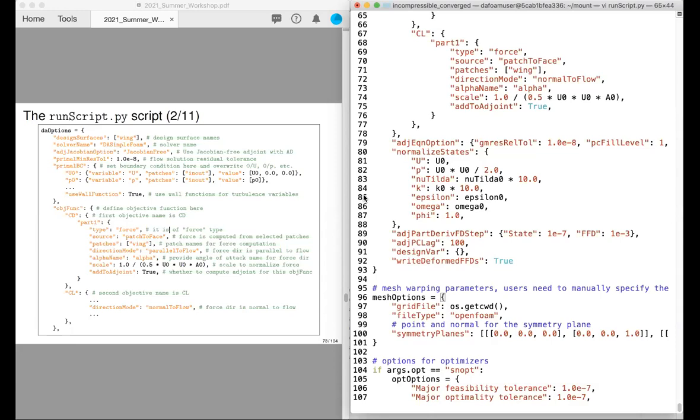That might create some confusion. Your FFD point blocks may slightly overlap, that's fine. But again, make sure that your geometry does not belong to two of the FFD blocks. Does that answer your question? All right, I hope yes.